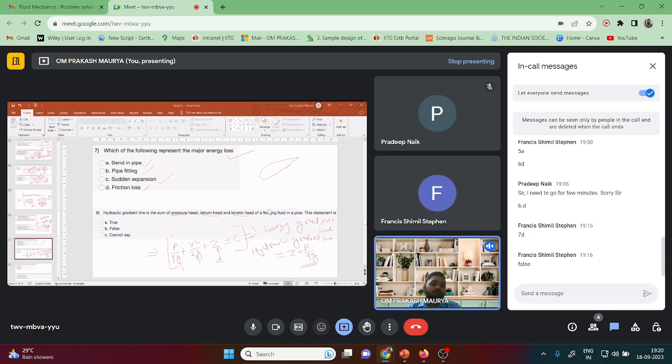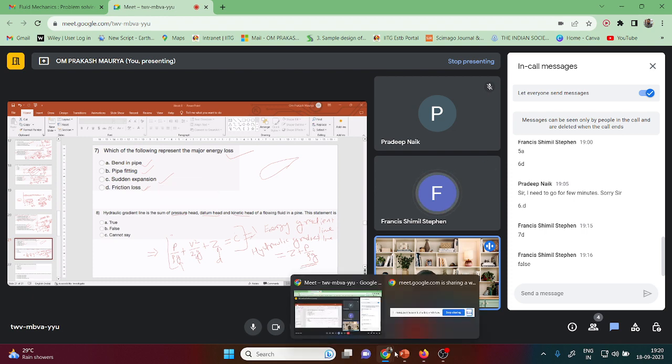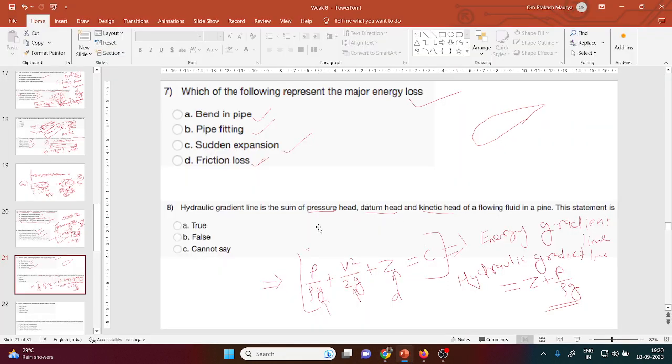Basically, in case of datum, you can select it anywhere. For example, this is a pipe flow case. Let's say the pipe is flowing like that, or maybe downward here. So your datum you can select here also. Arbitrary means you can select here also, or in the middle also. But you need to remember that your assumption should be similar everywhere: positive when you go up.